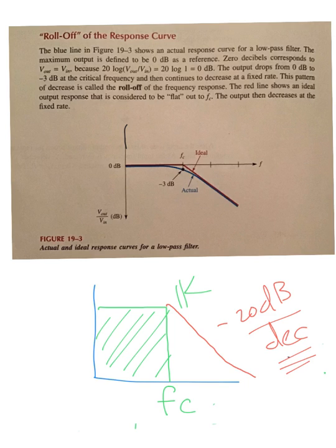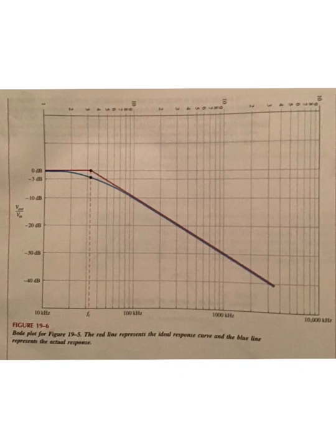It might not be the green box over here. It might not be this green box nice. It's a little bit sluggish, which means when you're trying to cut off at 1,000 hertz, you might get 1.1K, 1.2K, 1.4K bleeding into your circuit, which is not always a bad thing if you can tolerate it.